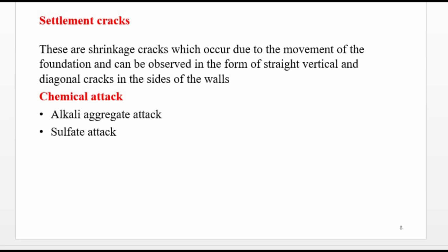cause cracking. So the other chemical attacks on concrete include acid, some alkalis, and numerous salt solutions. When the structure is near the seashore or is an offshore structure, the building is prone to a chloride attack. Also numerous salt solutions and organics such as fermenting liquid, sugars and animal oils.